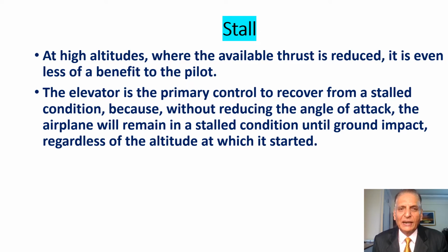The elevator is the primary control to recover from a stalled condition because without reducing the angle of attack, the airplane will remain in a stalled condition until ground impact, regardless of the altitude at which it started.